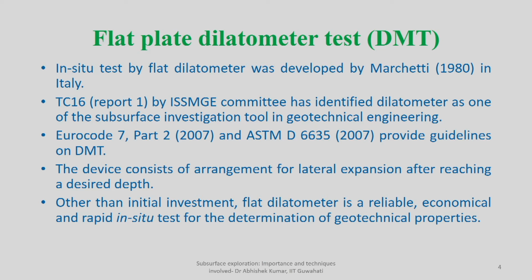Different technical committees exist for earthquake geotechnical engineering, for deep foundations, for retaining structures. This one in particular was recommended by Technical Committee 16. Similarly, Eurocode, another standard guideline provider, Eurocode 7 Part 2 in 2007, as well as ASTM D6635 in 2007, also provide guidelines about the dilatometer test: how to use the test and how to go about the interpretation.